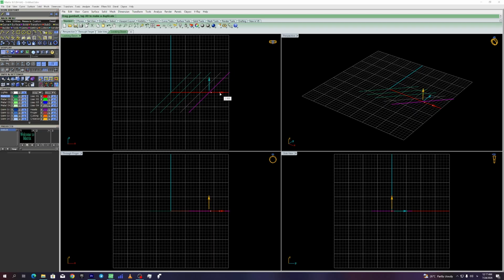If you want to copy your object in a straight line, either horizontally, vertically, or perpendicular, simply hold down the Shift key while you drag, and then tap Alt to make the copy. This combines the Ortho constraint with the copy function. Super useful for precise layouts.